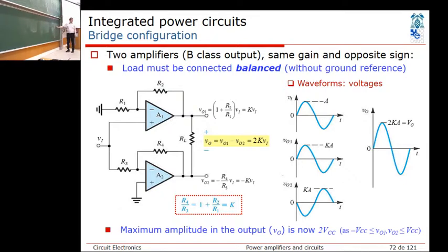the loudspeaker. So if RL is 4 ohms, and VCC, a single-sided VCC, is 12 volts, you don't get much power out of that one. But if you can quadruple it, you start getting a nice zoom, zoom, zoom on your car stereo. You don't need subwoofers for that power yet, but if you quadruple it, then you can.